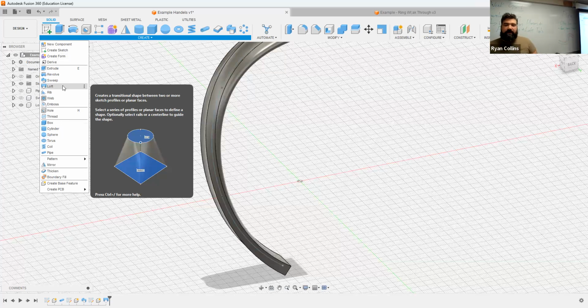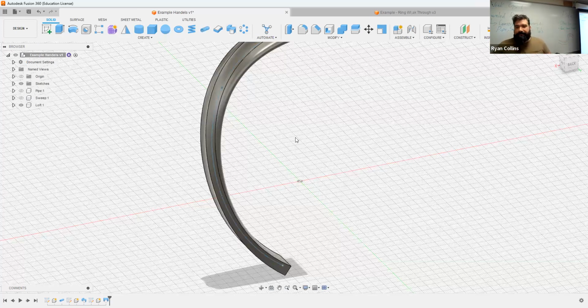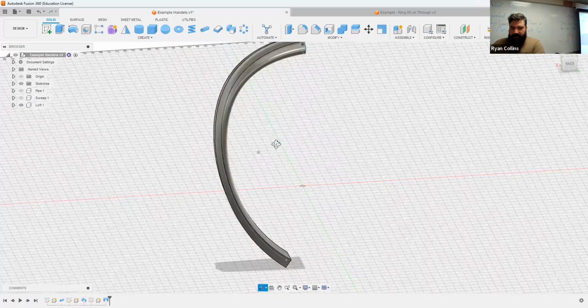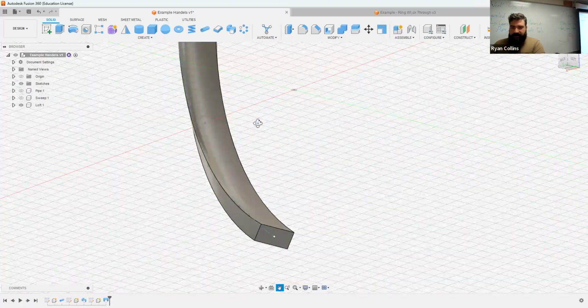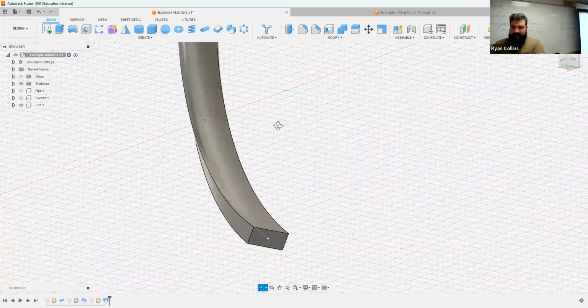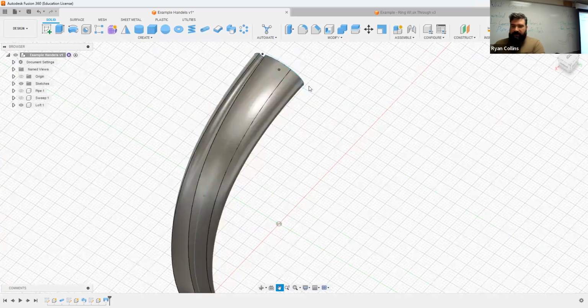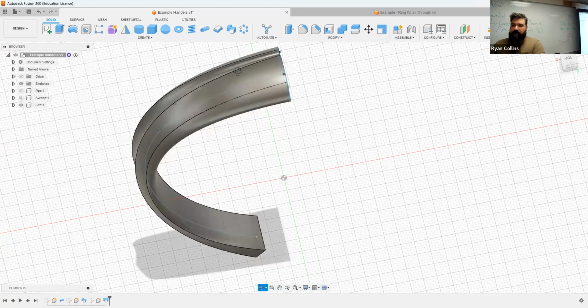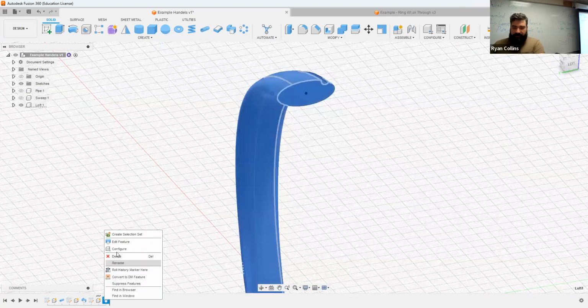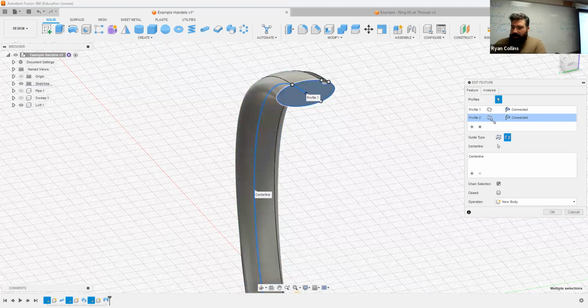The optional rails are exactly what we're using. That center line is our sketch. Same deal though, you can see the transition points there. It's pretty neat. It goes directly from square, sweeps upward, and becomes an oval. You can play around with the edit features here, only with a loft you have far fewer controls.